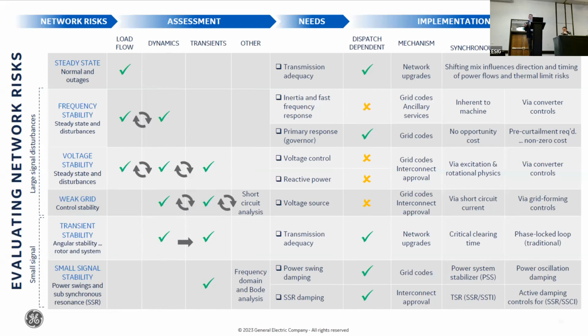The problem here is that power flows are typically either a min load state or max load state, and they don't really optimize the dispatch of generation for either of those two analyses. So sometimes it's a judgment call, where the generators will be set at that max load state when they do the power flow, or alternatively for the min load state. But it's not really incorporating the economic dispatch on the system. And that's why we found that having this round trip analysis is really beneficial.